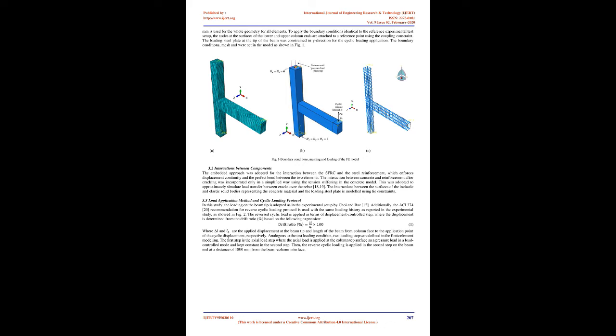Furthermore, because of the difficulties in integrating the compressive column axial loading in the experimental setup, it is common practice to assume the column axial load to be zero or constant in most of the research [16]. Nonlinear finite element analysis, however, can be viewed as a convenient and reliable solution to investigate such effects. In this study, the seismic behavior of SFRC beam column joints under the variation of axial load is carried out using the finite element software ABAQUS/Standard.